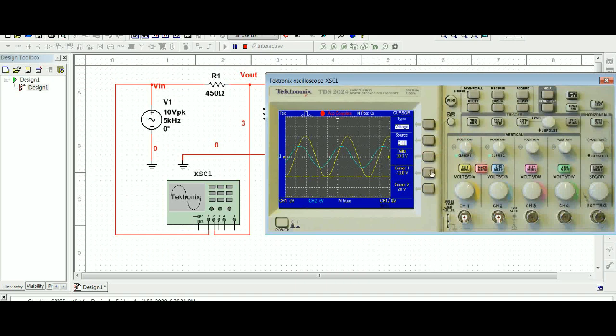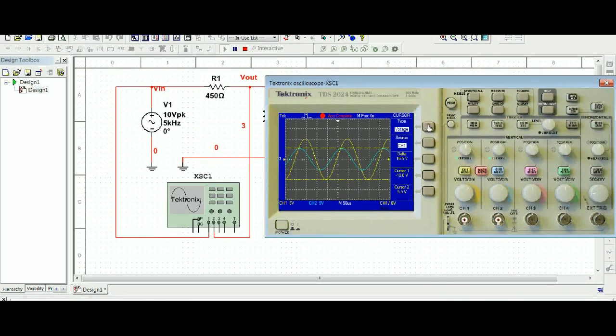Perfectly fine. Likewise, I'll bring a cursor here down from the top, and for the heck of it I'll set it on the output waveform. It's just about there, and I see that cursor is at 5.5 volts, which is pretty close to being correct. Now to do a phase measurement, and I would be writing these down if this were part of the lab, I'll click on this again, and now I'm going to select time. So we can't select phase in this, but if we select time and we know the period, it's a very simple matter of getting phase.